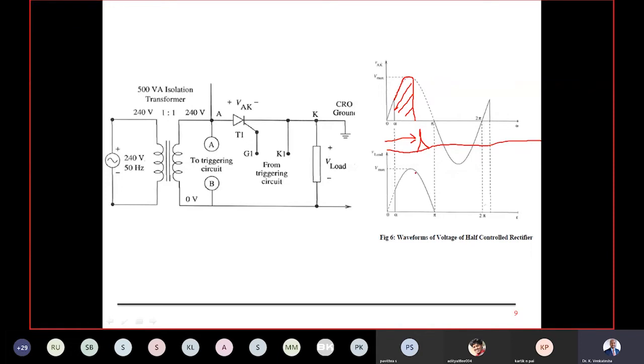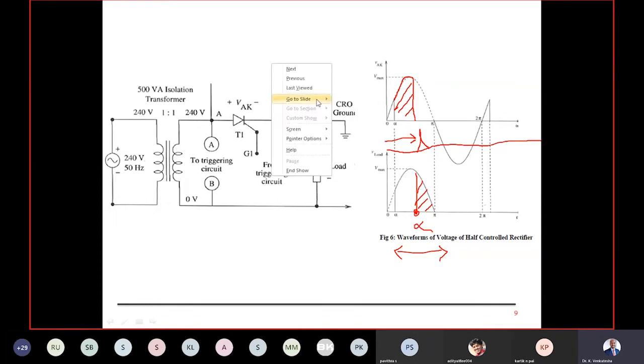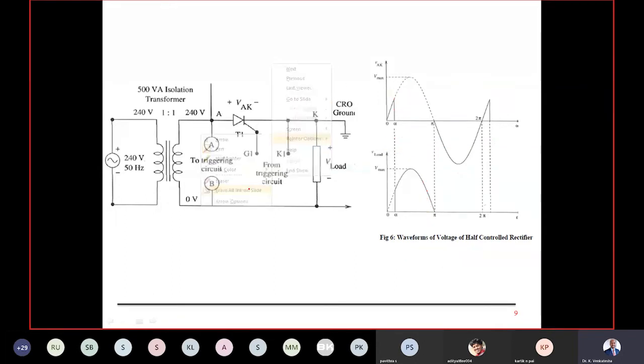Till here I'll be getting the supply voltage across my SCR. At firing angle alpha, from here onwards, I'll get the remaining portion across my load, because at this point I've given the firing angle. I can vary the firing angle from 0 to 180 anywhere, so the supply voltage waveform will be chopped. It will be chopped, which means, to tell you in a simple way: